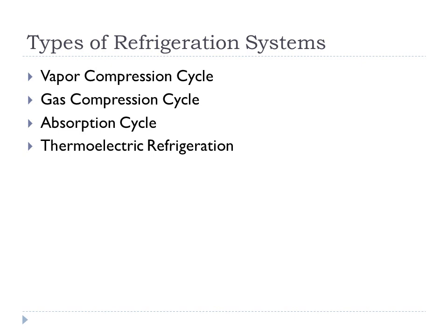Vapor compression cycle is the cycle in which we use a refrigerant which alternatively is in vapor phase and in liquid phase. The vapor phase of refrigerant is compressed, then it is condensed, and later it is expanded and then vaporized. But in case of gas compression cycle, the refrigerant is a gas that remains always in gaseous phase.